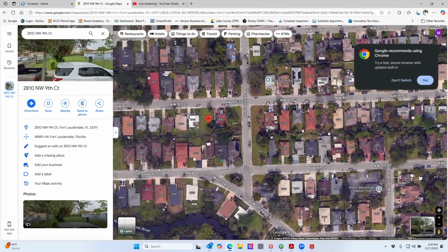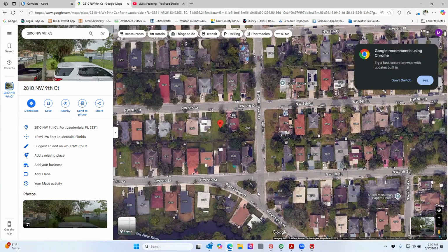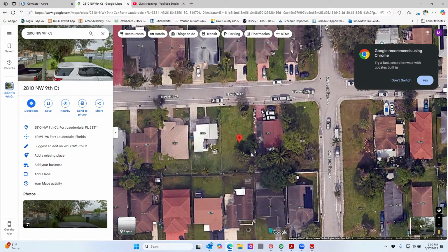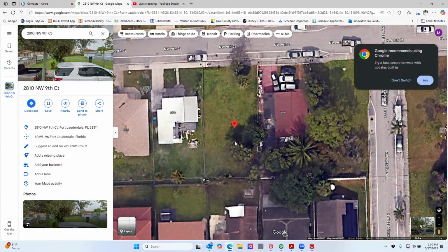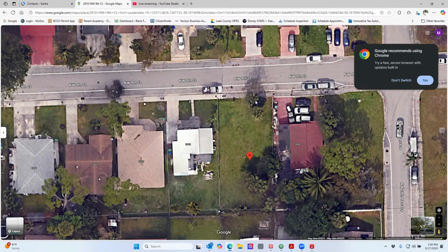And we see there's a way to see what date this is on these drawings, but it says imagery 2025 down here at the bottom. Because sometimes they may use an old image. But right now it looks like that image is current. So we see it's a vacant lot. So I want to see what's on the lot. Here's something else to note. Let's say these trees are still there, but it's not on the drawing. What are we going to do? RFI. Exactly. So normally, especially in the traditional route, we're going to send an RFI if these trees are not shown. Or we do a site visit, confirm they're there or not.